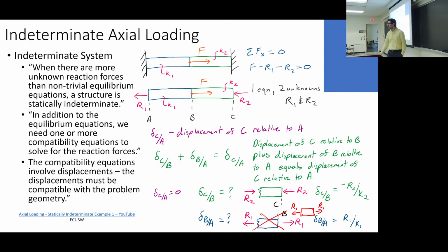I don't quite understand why R1 and R2 are facing the same direction if they're both in the same situation against a wall. Because I chose. Remember, with the reaction forces, I get to choose. This is not convention time. We're not going to convention when we're doing external loads, external constraints. This is me picking. I could have drawn them any way I wanted, left or right.